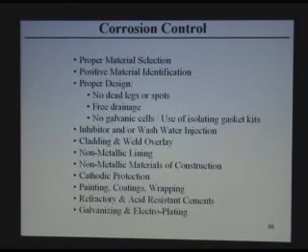A lot of materials like carbon steel and low alloy steel look alike when you look at them. And by mistake, fabricators can use carbon steel where you need chrome moly steel. In order to avoid that, once the fabricated item is delivered, you have to perform positive material identification.